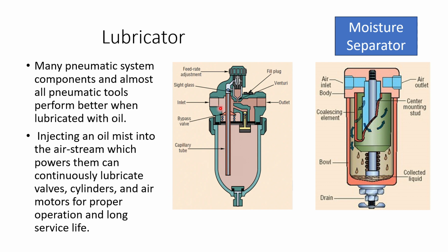So let us see how it works. You see, oil enters from here, and through this knob we can adjust the feed of the oil. Then the oil comes down through this capillary, and then it takes a U-turn and goes up, and from here it goes out.